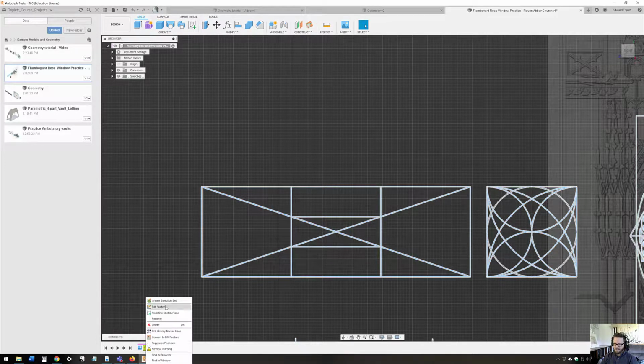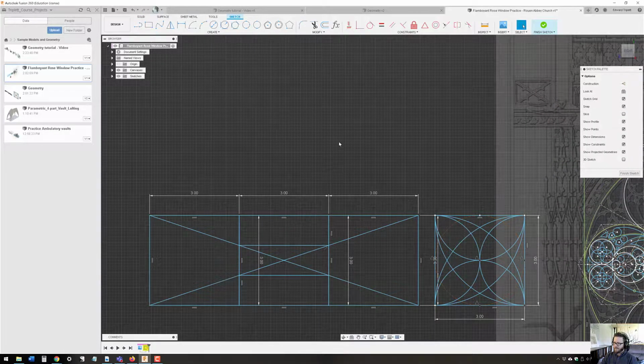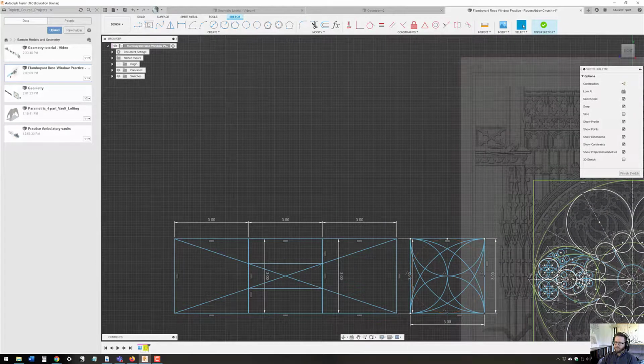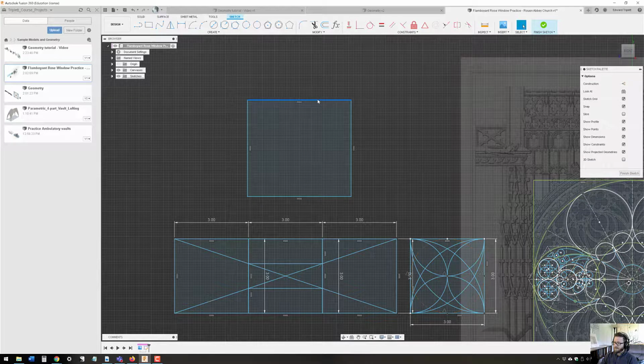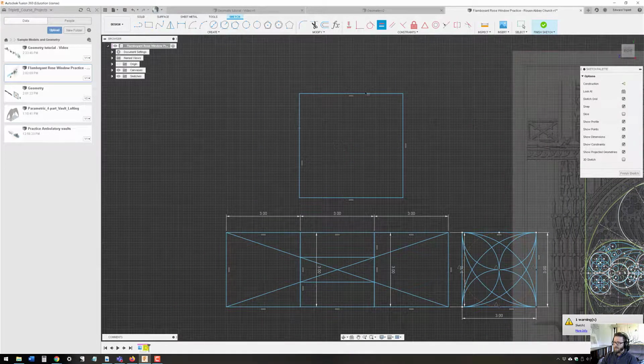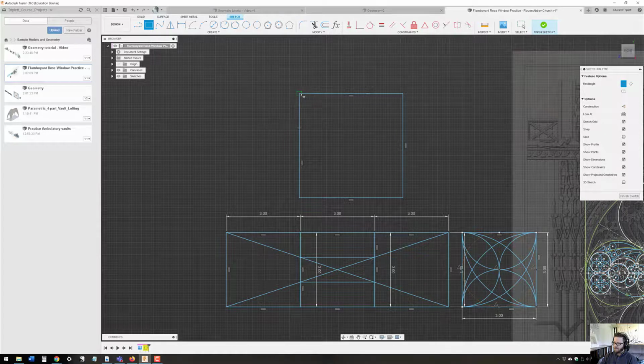Let's edit this sketch. So these are 3, 3, 3, right? If I really wanted to, I could have an arbitrary anything, right? I want to make sure that this stays square, so I'll say that this line needs to be equal to this line. Okay, so it's square. But what if I don't know, right? If I don't know what the measure of this is, you could easily get into this situation where you didn't have a straight line that you knew what it was automatically.